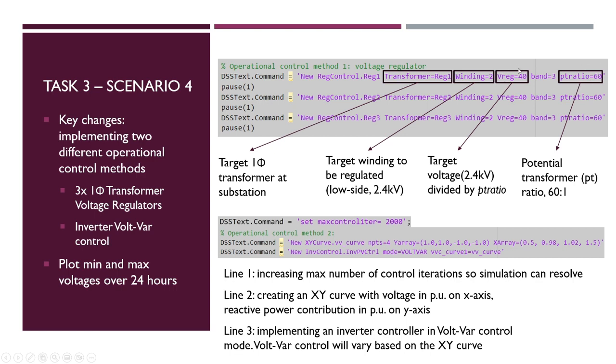So really, these are two flexible numbers. You can make this, say, 1,000. You can make this 2.4. You could... limits on practicality would be required to investigate, because at one point a 1,000 or 2,000 to 1 potential transformer would be impractical. I'm not certain about that. But I picked two slightly conservative values of 60 and 40. Multiplied together, they reach 2.4 kV, or 1 per unit.